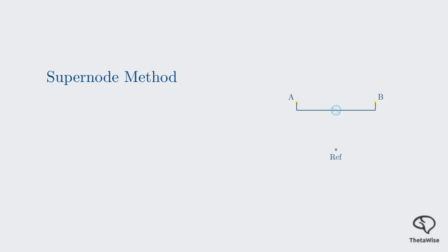We then apply KCL to the terminals of this combined supernode. The key is that the sum of all currents entering and leaving this entire region must be zero. This gives us one equation. But just like with the supermesh, we need a second equation. This comes from the voltage source itself.